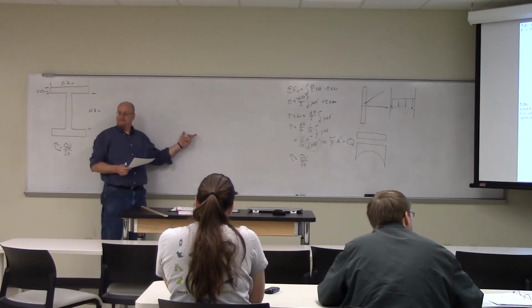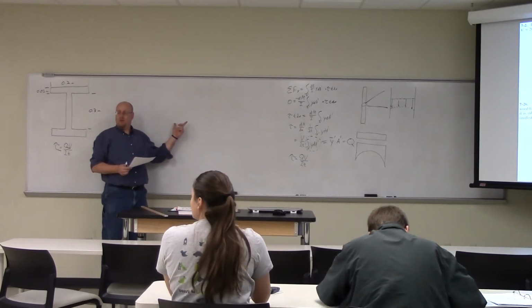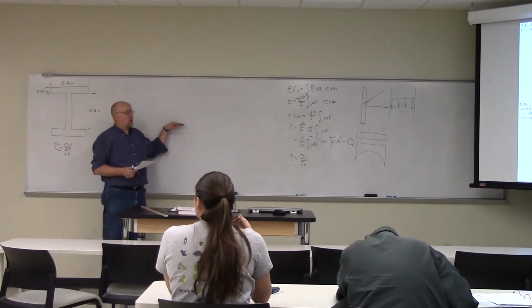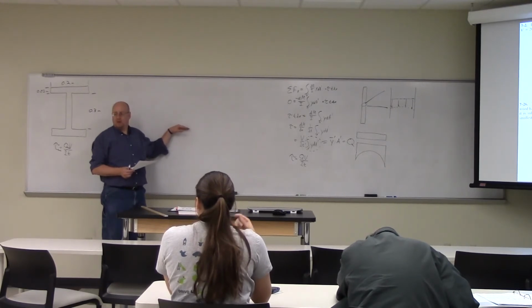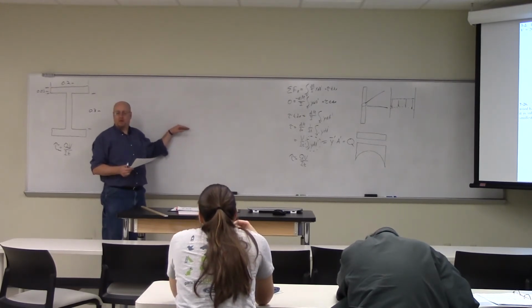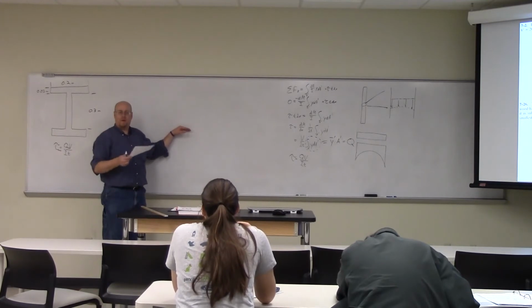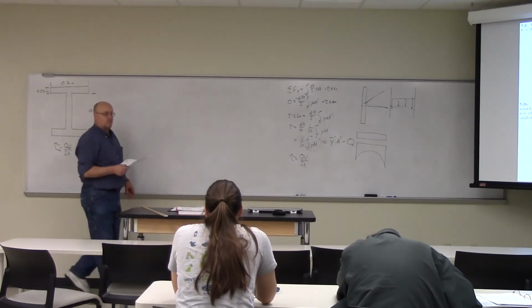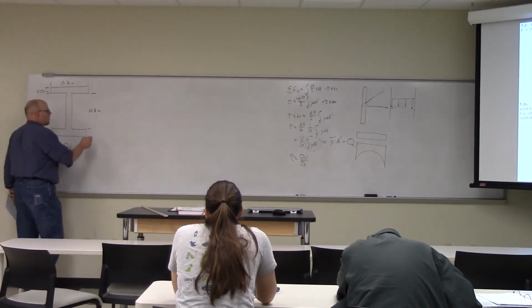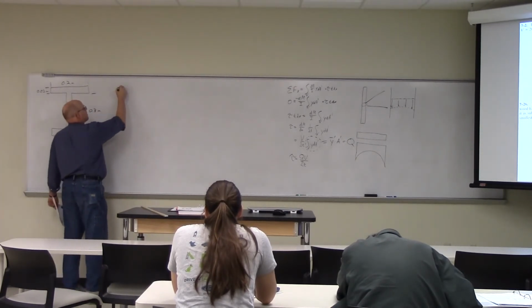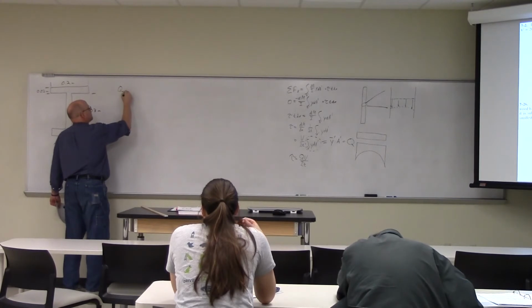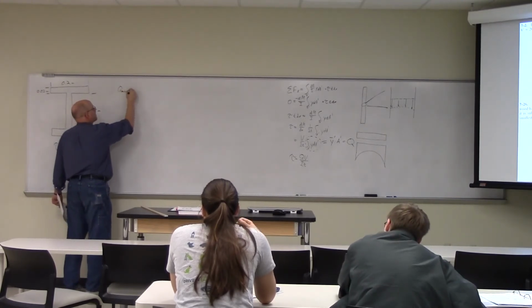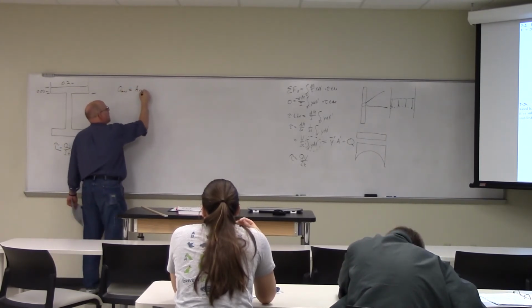So we need to find the value at the neutral axis. We always know that tau max occurs at the neutral axis. So you would take the area above the neutral axis, and then the centroid, y bar prime, with respect to the center line?